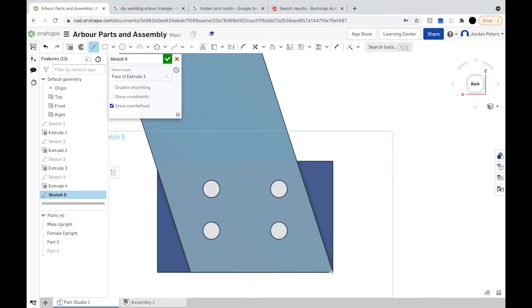And we're going to draw some lines, 40 mil in, 40 mil, 30 mil up, 30 mil up. Oh, don't want it in line with anything. It locked to a different line, so I just redid it. Make sure I'm not constrained, like I said last time. 50 mil across and 30 mil down.